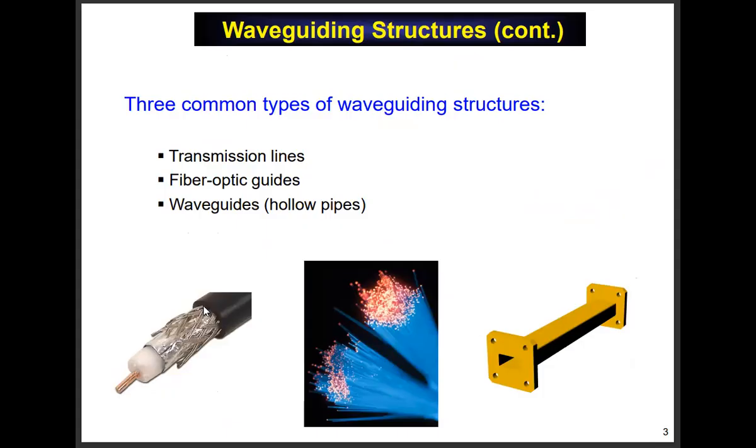So if you try to pump more and more power through the coax, where's the electric field going to be the strongest? Right close to the inner wire. Okay. And because if that wire is skinny, then there could be a huge field there. So you don't have to pump too much power down the coax before the electric field gets so strong near that skinny wire that the dielectric starts breaking down. Okay. And because of the really high surface currents there, it's got a huge amount of loss compared to the waveguide because the surface current is so high.